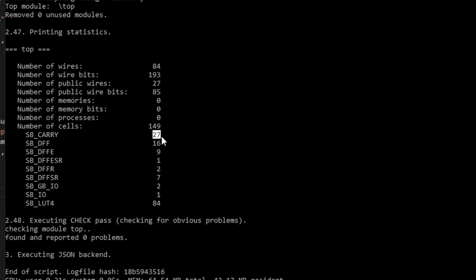But the problem with linear feedback shift registers is that you really have to step through the shift register one by one in order to determine what the actual output is. So it doesn't go 0, 1, 2, 3, 4. It may go 1, 15, 4, 17, 95.